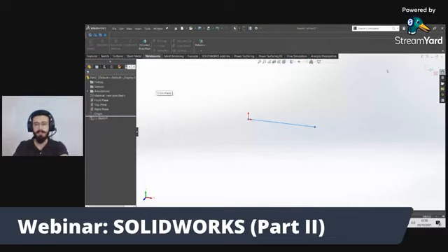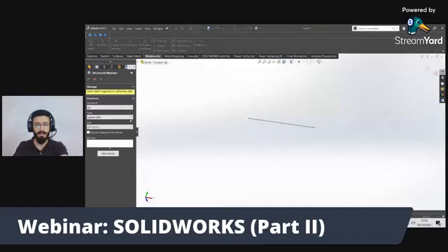In weldments, you first finish the sketch. Our sketch is ready. Then go to weldments, and there is an option, structural member. Just click on it. Now there is a drop down menu which contains standard, type, size, and groups. What is standard? Standard is the standards of dimensions used in a country, like ANSI, AS, BS, CNSI, DIN, GB, ISO. People mostly use ISO and ANSI. These are the standards mostly used in Pakistan, or mostly the international standards. So we'll be using standards.